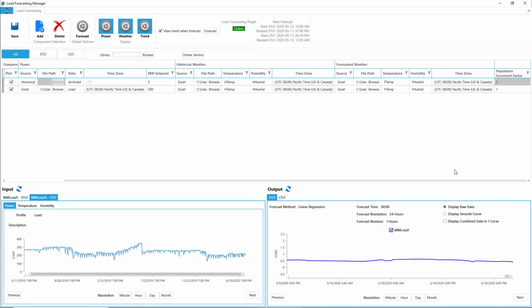One more important tool is the load and generation forecasting tool. The forecasting application utilizes the weather information, historical and forecasted, as well as the power historical data and current operating conditions to forecast generation and loading up to 1 month ahead in the case of short-term forecasting and years for long-term. The configuration is performed and variables for the forecasting can be configured. Here at the bottom we see the historical data utilized for the calculations, and at the right is the forecasted output. This information is utilized by the controller to perform decisions on the dispatch.